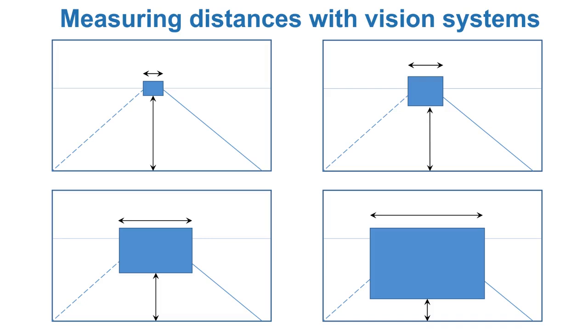Imagine following a lead vehicle, the blue box in the image. At any point in time, the object has a size on the camera, in pixels, and the lower part of the vehicle will be a specific number of pixels from, say, the bottom of the image. As the object gets closer, the size will increase and the number of pixels from the bottom of the vehicle to the bottom of the image will be reduced. The latter assumes that the ground is flat, hence the flat earth base name. The distance is proportional to the gap, in pixels, between the object and the lower part of the screen.